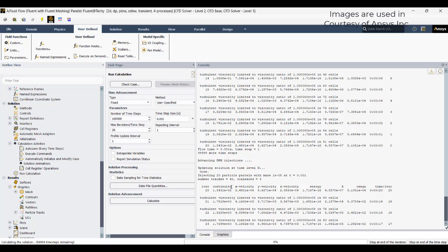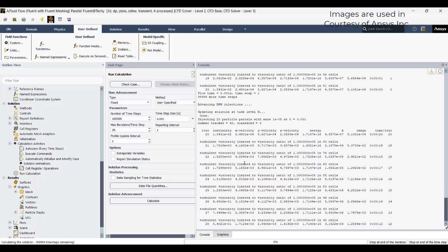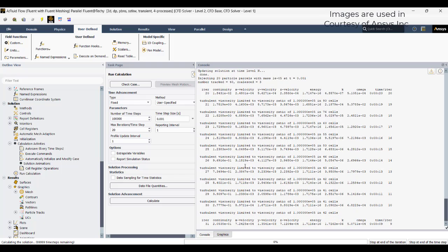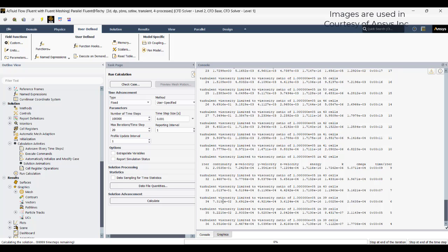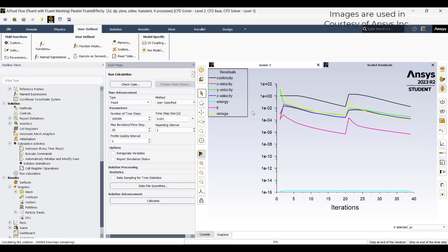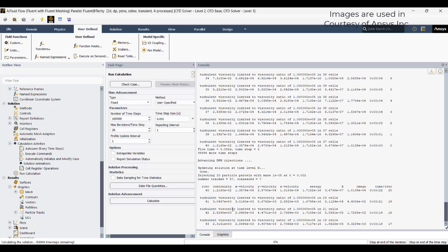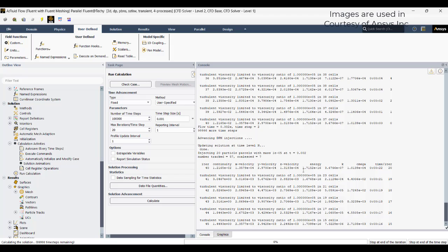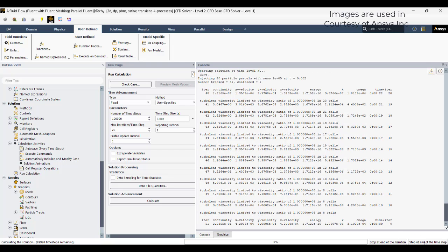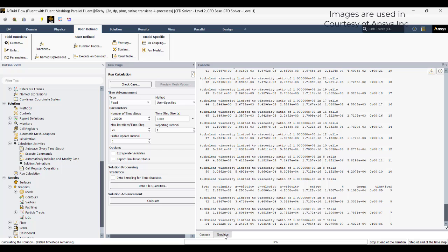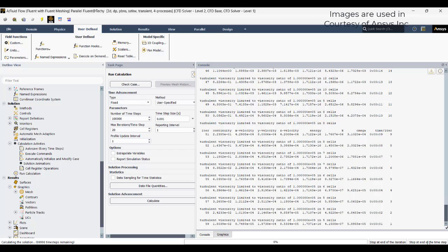So now another 20 particle parcels are injected, and 3 particle parcels have been coalesced or combined depending on the stochastic collision on the probability basis. So let another time step also run so that I can show you something on the screen, how the particle parcels will be injected. Now another 20, and again 7 particle parcels have been coalesced. Let it run. Okay, then maybe another 40 iterations. So we'll leave it for another 40 iterations and we'll check.